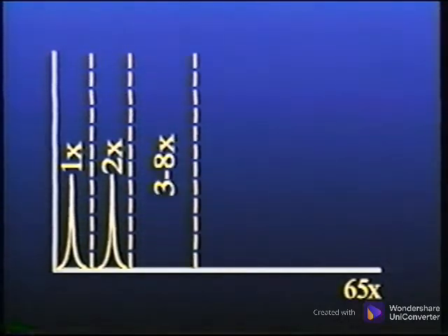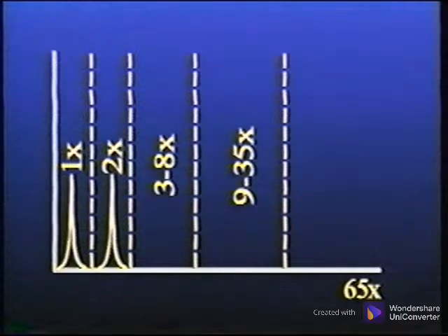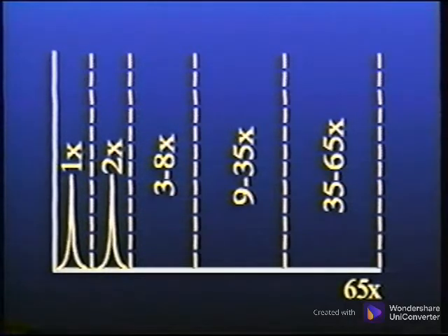A band set from 2.5 to 8.5 orders covers looseness and vane pass. The next 2 bands are bearing bands. The first bearing band spans from 8.5 to 35.5 orders. The second bearing band spans from 35.5 to 65 orders. The sixth band, as mentioned earlier, is used for the variable high-frequency band from 1 to 20 kilohertz.